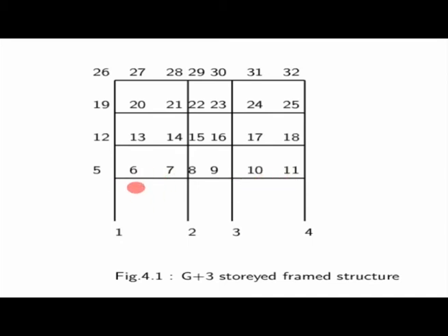So that I can get bending moment and shear force immediately at the middle. So like that I am having 2 plus 2 plus 2, 6, 1, 2, 3, 4, so 24. That means there are 16 columns and 24 beams. So total 40 elements. So I have 32 nodes and 40 elements.